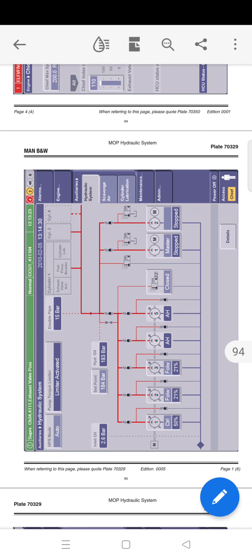So SPS mode guys, SPS mode has 2 modes. Pressing the SPS mode button, you can see SPS mode in auto. So it is basically auto and manual mode. In auto mode, it is possible to perform the following commands, both operator and chief level. Select one of the electrically driven pumps as master. There are 2 electrically driven pumps, so you can select one of them as master. Select one of the engine driven pumps as pressure controlling pump.